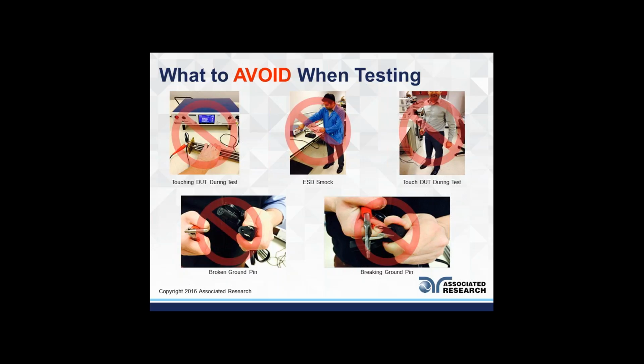In cases where you need to perform high voltage testing with the leads coming in contact with the operator, you want to make sure they have personal protective equipment like high voltage gloves, things of that nature, so they're not coming in contact with the high voltage and the operators are safe.